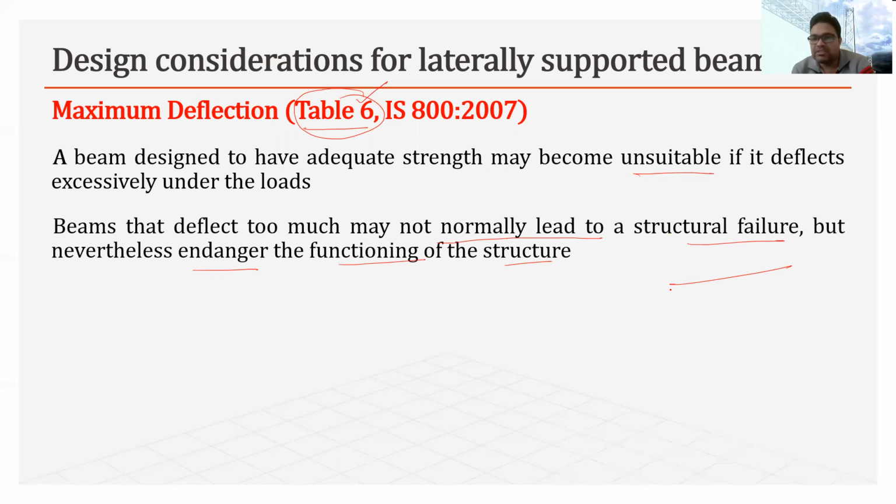Like if this is the beam carrying a load, and because of this load it is deflecting like this, this is the deflection. If this deflection is higher, any occupant may feel uncomfortable. In that case, the functioning of the beam or the structure will be endangered.